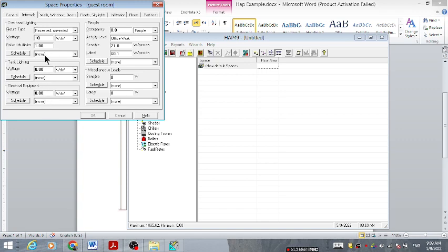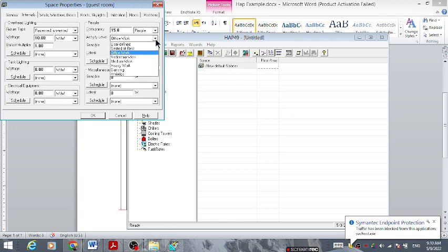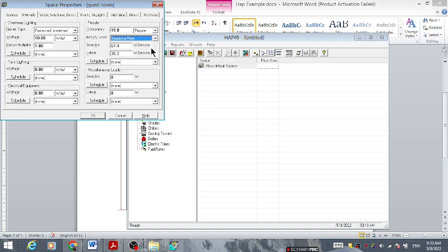The very important information or factor to consider in this window is the occupancy. Occupancy is a very large, considerable heat source. So how many people do you have in this space? Let's say 15 maximum. What type of work? It's seated at rest. This is a guest room, so seated at rest. You can see here the sensible and latent cooling load will be different. So choose seated at rest.